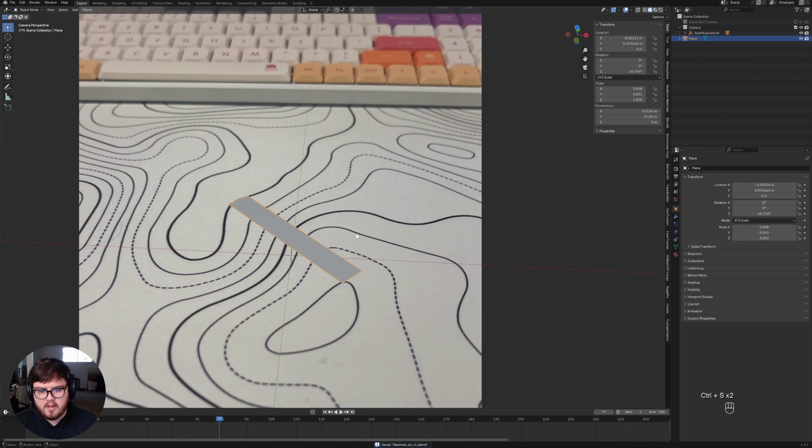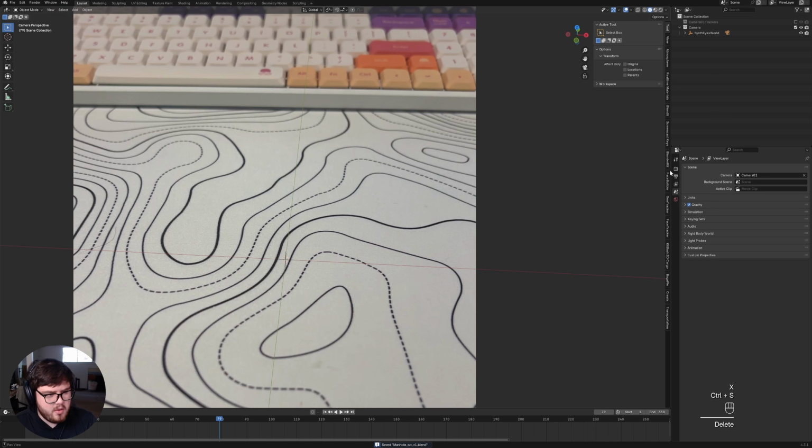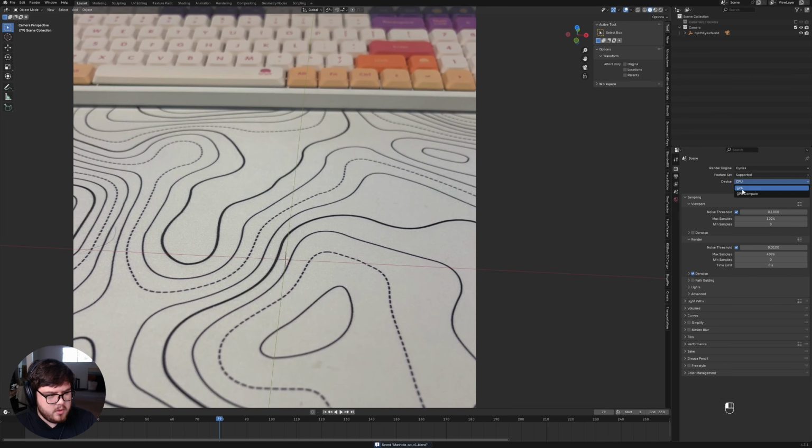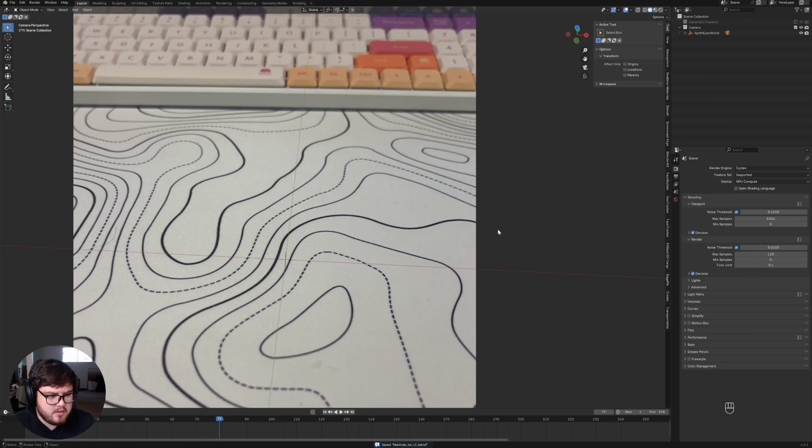Okay, so let's go ahead and start doing some CGI and some fun stuff there. So first thing I always like to do is switch it to Cycles. Then we're going to do GPU compute, denoise the viewport, and then I'm going to set the sample count to 128 for now. We can always change it up in a little bit. Also, since we're rendering at 4K, we don't really need to render at 4K until the final render. So I'm going to set this to 50% just so it renders a little bit faster in the preview phase so we can make decisions faster there.